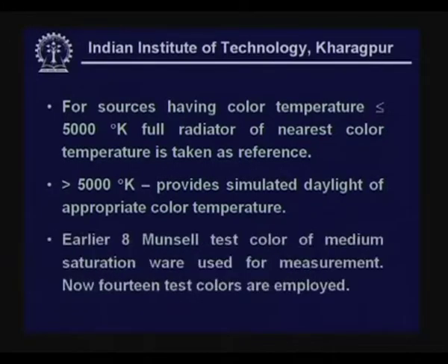Earlier, 8 Munsell test colors of medium saturation were used for measurement, and now 14 test colors are employed. Recall that the test colors are placed under the test lamp as well as under the reference lamp, and the shift in chromaticity is observed, and that is specified as color rendering.